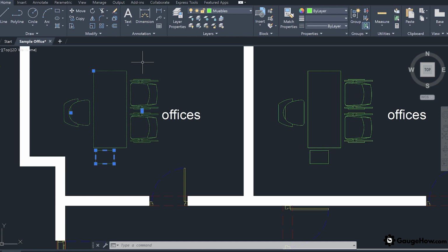And that highlighted objects are selected. Again, hit the escape button to deselect all the objects. So from these three different methods, it is better as a beginner you use windowing and crossing for the object selection. Keep practicing these tools for better understanding the selection of objects.